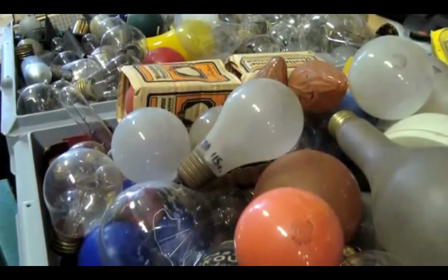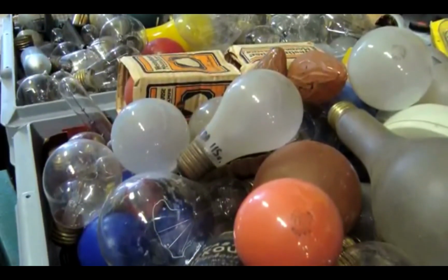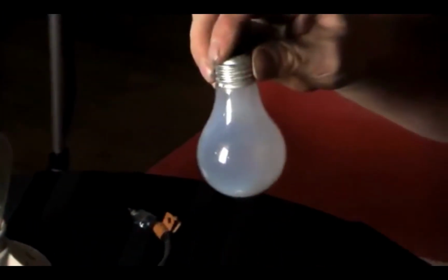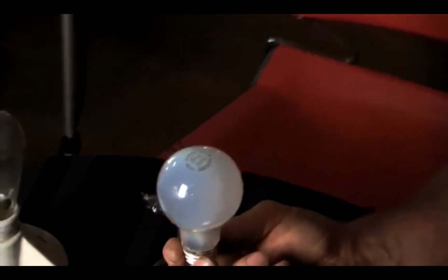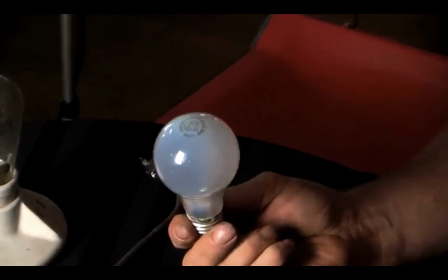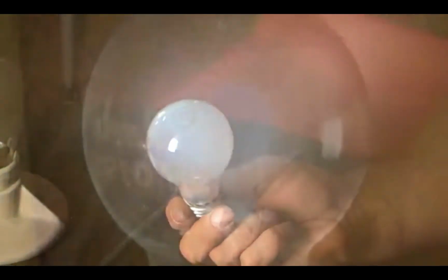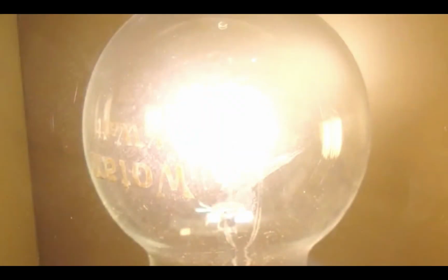Plus, it reduces blackening of the glass because the blackening goes to the highest part of the bulb. If it's base up, it'll be here. If it's horizontal, it'll be here. And if it's base down, it'll be here. So the whole bulb doesn't blacken like a vacuum bulb does, and the bulb will maintain better light output throughout life, which is another advantage of gas filling.